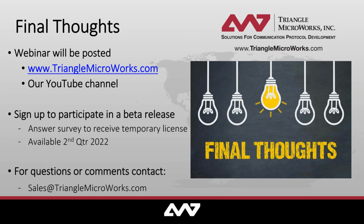Typically in our system, the way we can monitor GOOSE is by simply monitoring for point changes or attribute changes. Suppose the GOOSE that you want to monitor is between the outstation and the gateway, so it's on the bottom half of the diagram. One way we would look at that is we would simply see changes in the model of the device in the gateway, and we could monitor these point changes, which are a result of the GOOSE stream, but we don't actually look at the GOOSE message in that case. We're simply looking at the results of receiving a GOOSE message.